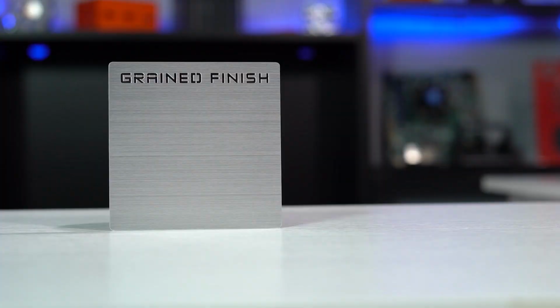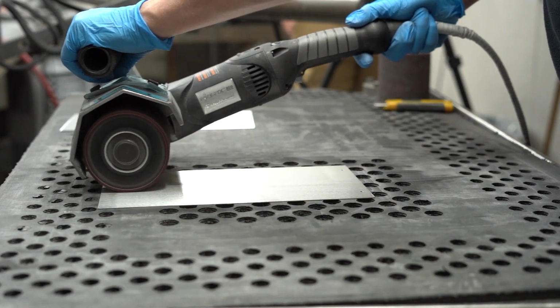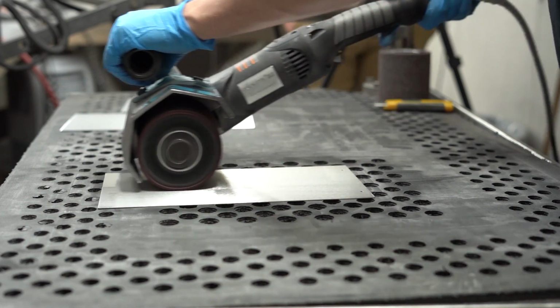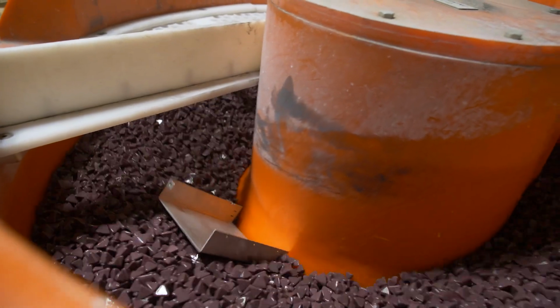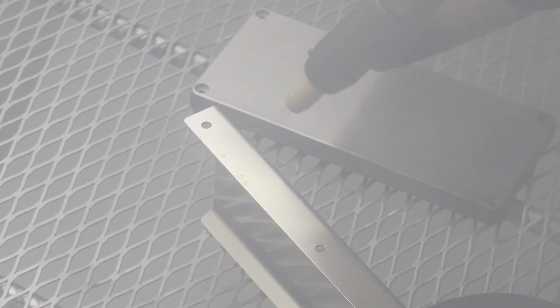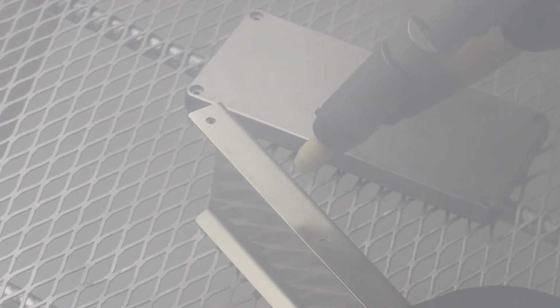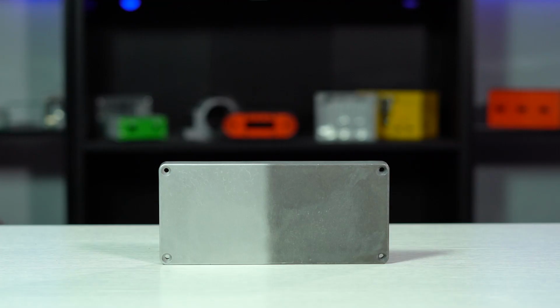If your enclosure or parts will be on display in any professional manner, we don't recommend opting for no finish. Instead, we would recommend using a grain finish, vibratory finish, or media blasting for your parts if you prefer a bare metal look. For grain finish, a part is deburred then given a specific linear grain direction via brushing. Vibratory finish smooths and imparts a random finish via tumbling in abrasive medium. For media blasting, the part is deburred and cleaned, then sprayed with a steady stream of tiny glass beads via compressed air to create a smooth, uniform finish that's flat and non-directional.